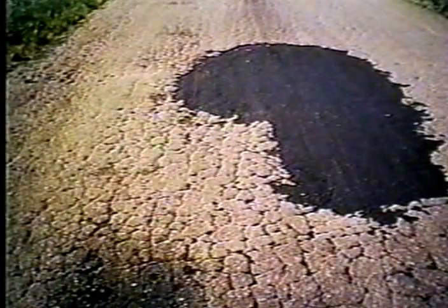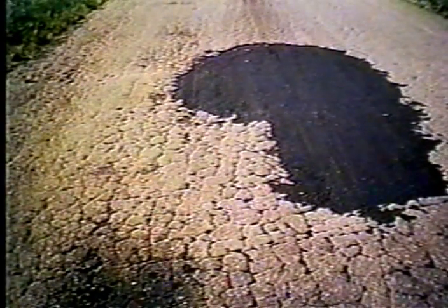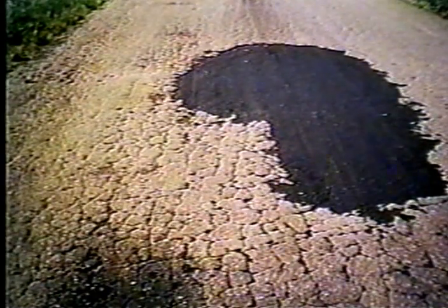But if you put down a patch or a wedge in an asphalt pavement, and within 6 months or a year you begin to see it fail, that says really inherently this pavement is not sound, and a more extensive rebuilding is likely going to be required. So you can learn a lot by just looking at the performance of our patches and repairs.